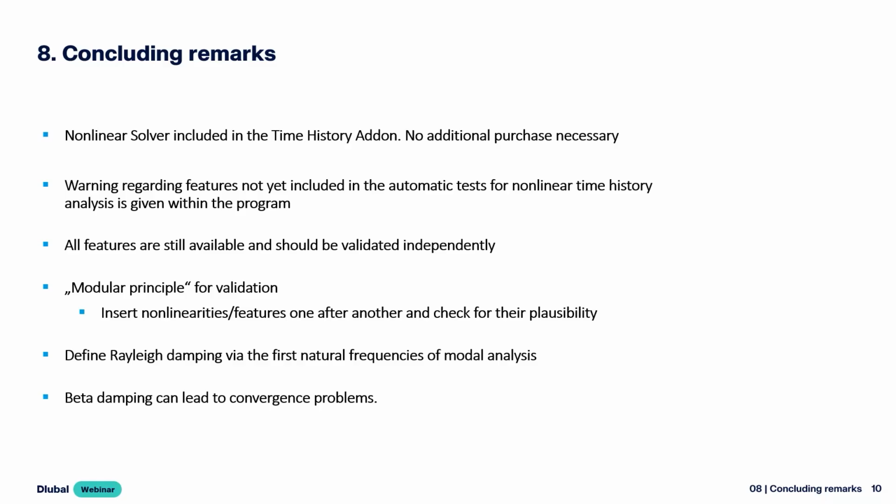So that's the next tip from myself. It's something I call the Bausteinprinzip, modular principle, for the validation, because in RFEM 5 I got lots of customer models which just had tons of non-linearities mixed, and they just said it's not converging. That's quite hard to investigate, where's the problem with that. So please insert one non-linearity or one problem after each other and investigate its plausibility. Otherwise you're just stuck with tons of calculation time or convergence issues, and it's going to take more time than building it up like that.